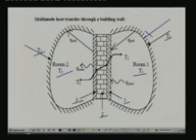Okay, and here the heat transfer is also by multi-mode. For example, heat transfer takes place first by radiation from the surrounding surfaces to the wall, and also by convection from the air to the wall. So you have radiation and convection heat transfer taking place from the surroundings and the air of room 1 to the wall. Okay, so the radiation and convection will be happening simultaneously. Then from this point onwards the heat transfer through this wall is by conduction. So you have initially radiation and convection, then conduction through the wall, and from the wall to room 2, which is at lower temperature, again the heat transfer is by radiation and by convection.